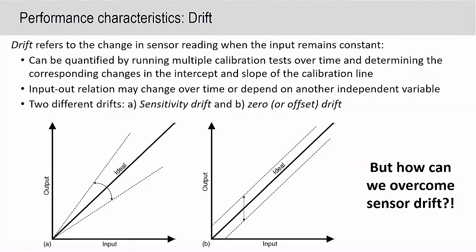And another thing you might be able to do is, if you can define the drift before you implant the sensor, then you might also be able to use a time-varying transfer function. We talked about nonlinear transfer functions before, but you could also potentially use time-varying transfer functions. This would only be if it's something consistent, if you know the drift, it's very well characterized.